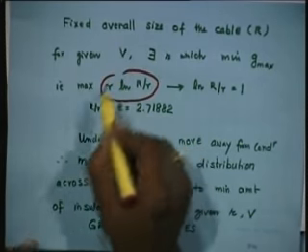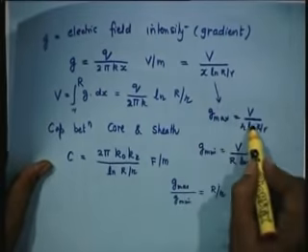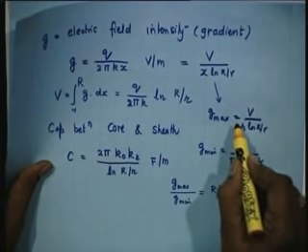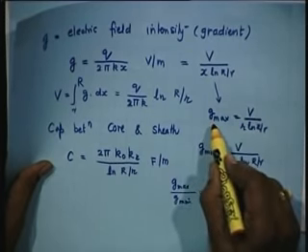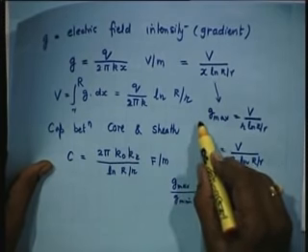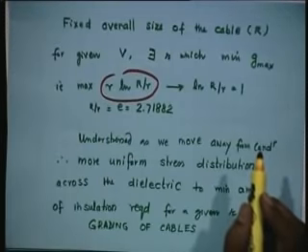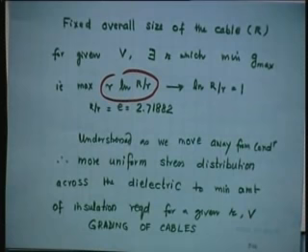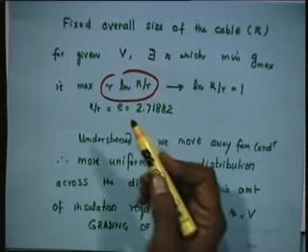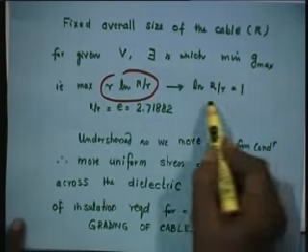Why do you want to maximize this quantity? Because if you want to minimize G max, you have to maximize the denominator, so that G max will be minimum. So, it is a min max problem, an optimization technique. You are minimizing the maximum value of G. So, this should be maximum. If you carry out this maximization problem, naturally the only variable is r. So, d by dr of this, put it equal to 0, solve it, and the answer is this.